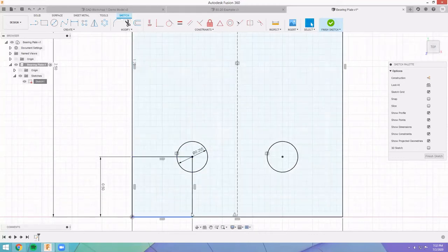We know that this rectangle was one thing. So if you actually double click any line, it'll grab the whole polygon that that line is a part of. And that'll work for this one too, right? Here's the whole polygon. So we'll just double click this one and we're going to make that entire thing a construction line by pressing X.